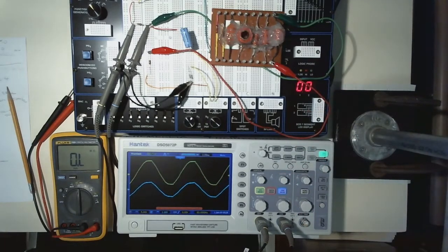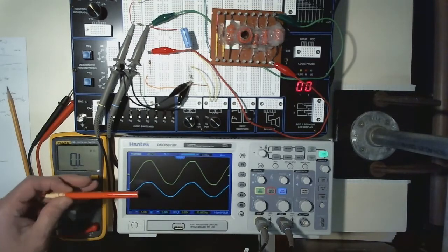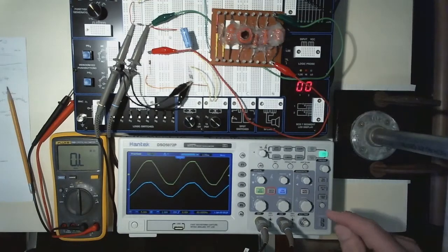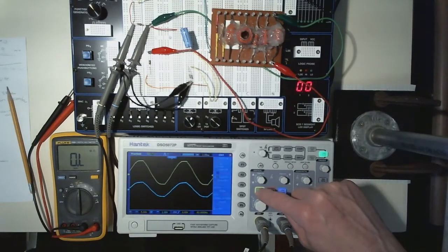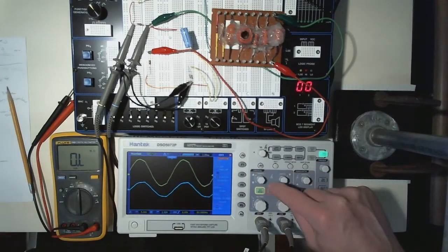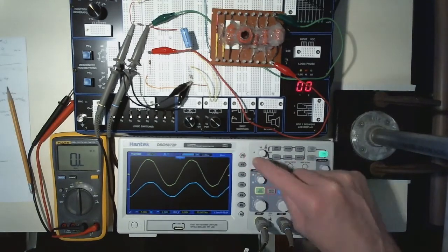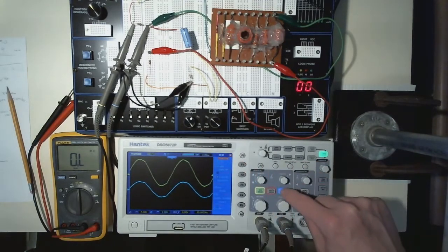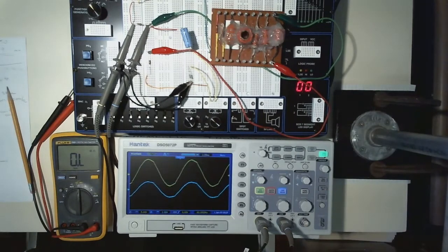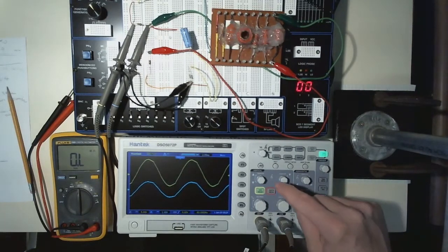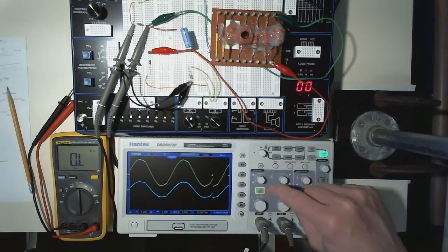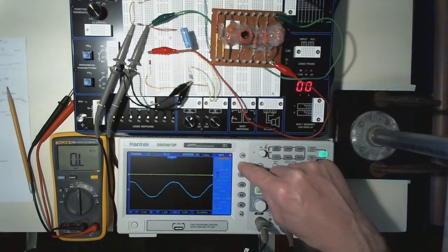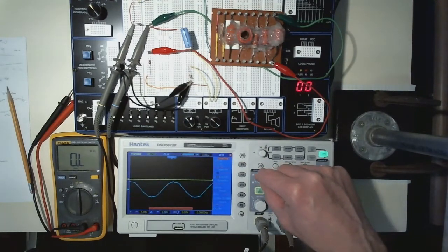a few ways to make sure that you're comparing apples to apples. What we want to do is we want to get these to reference this line right here. So a couple things that we can do. If I look at the menu here, I probably want to have both of these on AC. Look at the channel 2 menu, put those on AC. That's probably good. And then when I had the menu up, what you could do is you could have grounded that, and I can just do that. When you ground that, it goes down to 0, and then you could put that on the line there.